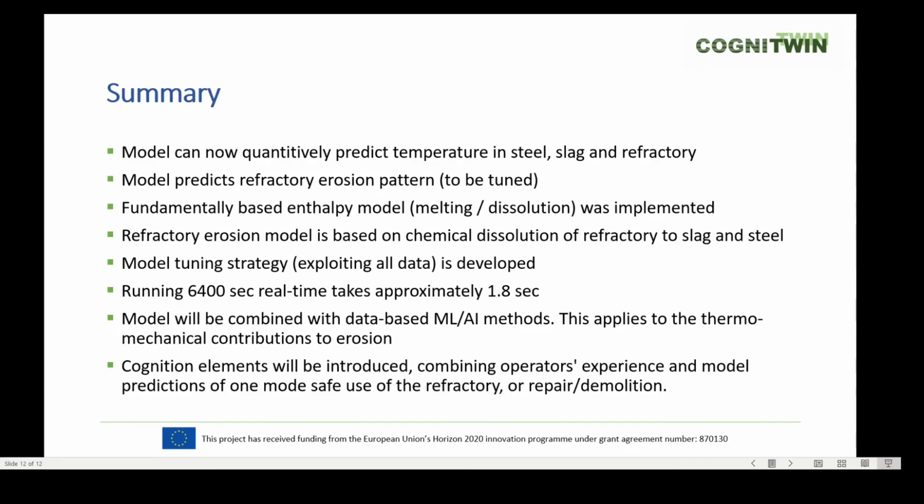That is remaining work. We have developed a fundamentally based enthalpy model to handle the melting and dissolution. This was implemented and is used for handling, in particular, the addition of slag former and other alloying materials into the ladle. We have a refractory erosion model which is based on chemical dissolution of the refractory, dissolving elements into the slag or into the steel phase. And we also developed a tuning strategy exploiting all the data.